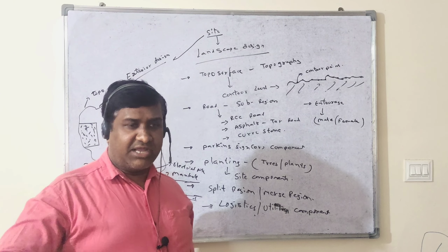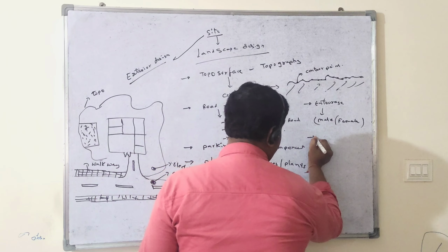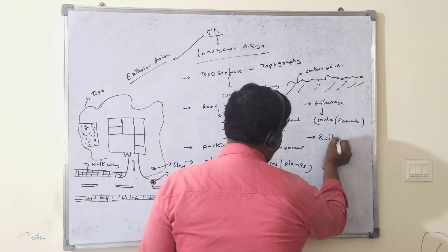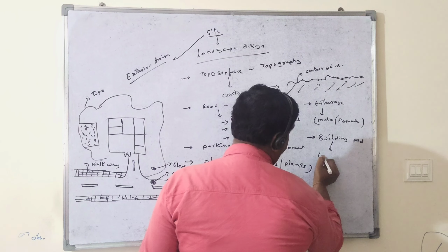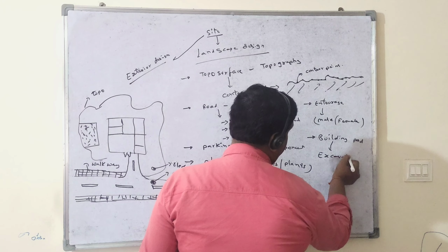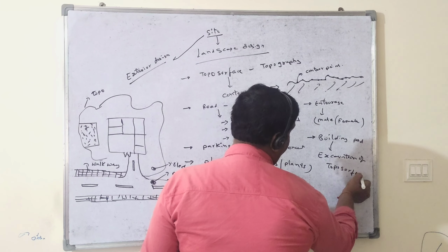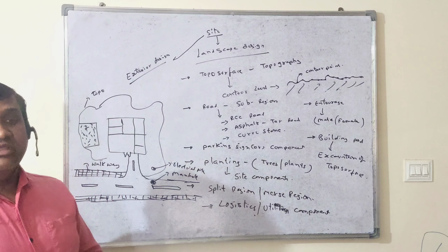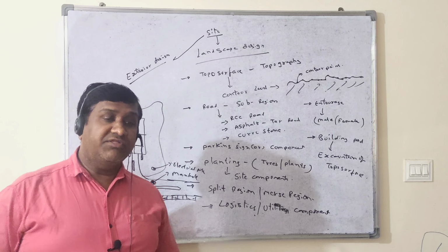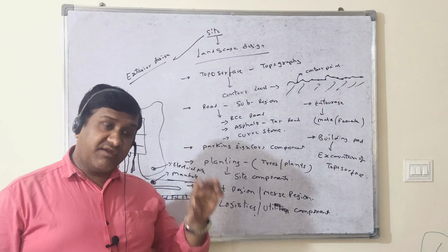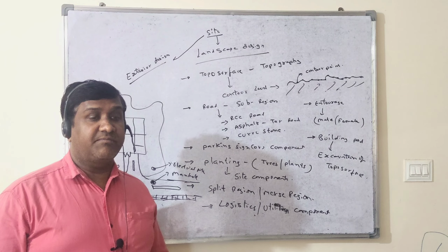And in your building surrounding area, some excavation has happened, some digging of the material, the mud has been taken out, that also we have to provide, and we will do that with the help of the building pad. There is an option called building pad. With the help of building pad, we can do excavation of the topo surface. So wherever you require any excavation, we can do it with the help of building pad, because that all comes under underground. The excavation length, the width, the size, everything we can take as information here.